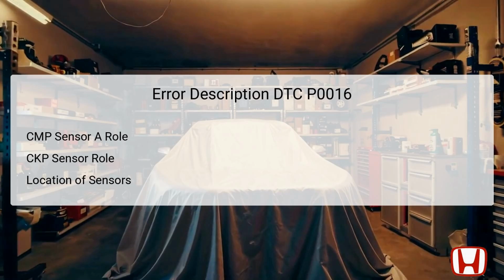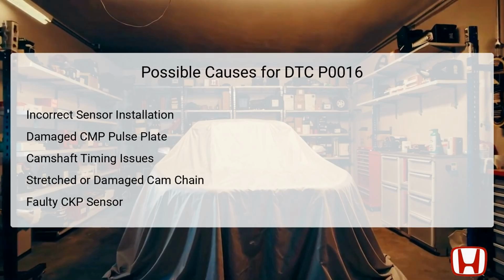Should either sensor fail or show a discrepancy in their readings, it can lead to poor engine performance, stalling, or difficulty starting. Diagnosing this DTC requires a comprehensive understanding of each sensor's function and accurate location in the vehicle. Several factors may lead to the occurrence of DTC P0016. An incorrect installation of either the CMP sensor A or CKP sensor can result in miscommunication between them and the engine control module. This emphasizes the importance of verifying proper sensor installation according to the manufacturer's specifications.